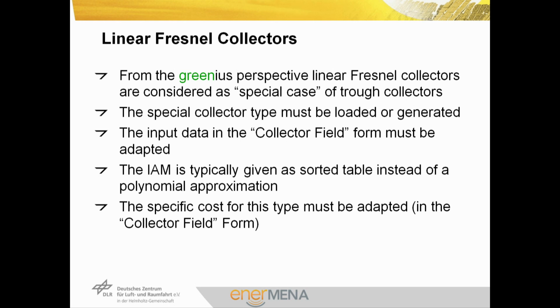If you're going to talk about linear Fresnel collectors, then they are, from the Greenius perspective, considered as a special case of trough collectors. So this special collector type must be loaded or generated, and the input data in the collector field form must be adapted. For linear Fresnel collectors, the incidence angle modifier is typically given as a tabulated table instead of a polynomial approximation. And also important, the specific cost for this type must be adapted, since it's typically cheaper per square meter than